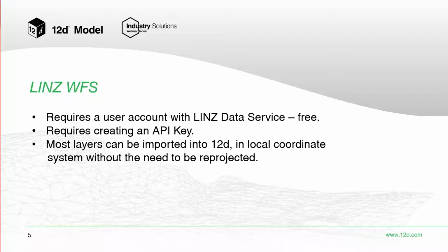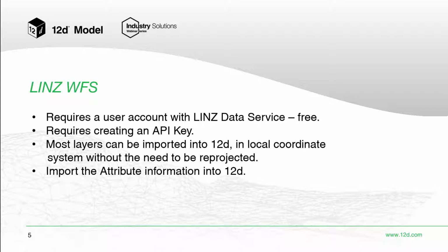When I say most layers, things like the LiDAR information, you still need to bring in the raw ASCII points from the LINZ data service, but you can consume the tile locations from the LINZ data service. When that information is imported into 12D, unlike some of the normal exports from LINZ data service, the data is not dumb, it actually has attribute information that you can use.